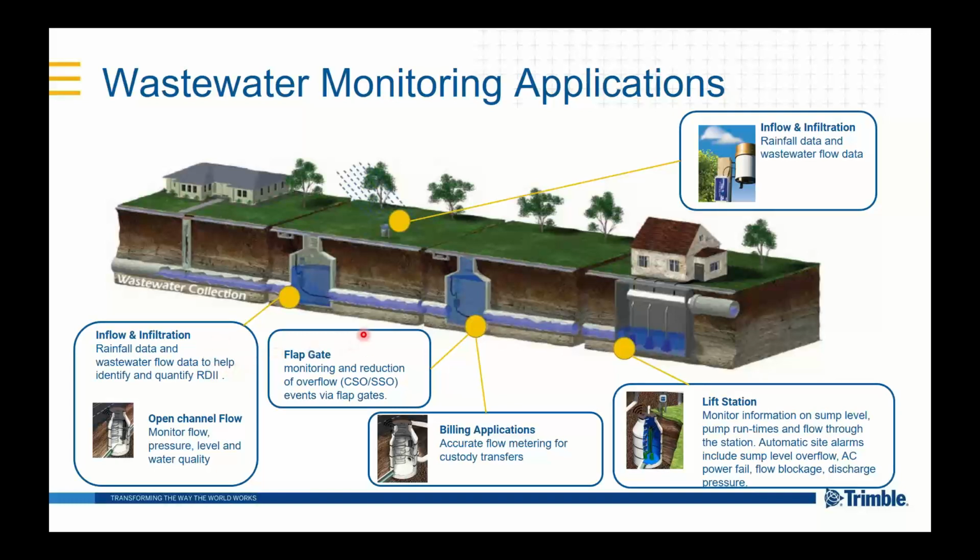We can also help you with SSOs and CSO monitoring as well. We can tie our equipment at flap gates or at tide gates in your system if you have a combined system, and we can check the events there and tell you when your flap gates are active and compare that to data that you're getting from your flow meter to see what sort of performance you're seeing out in your system.